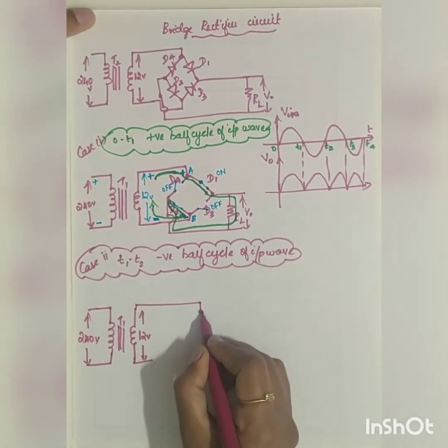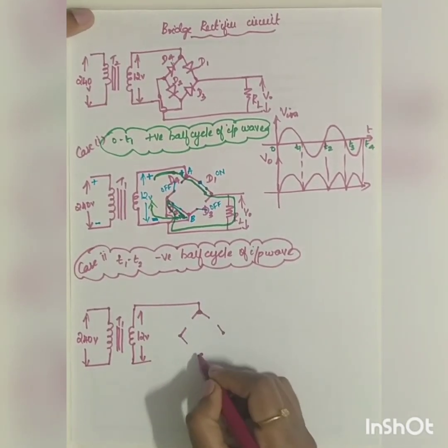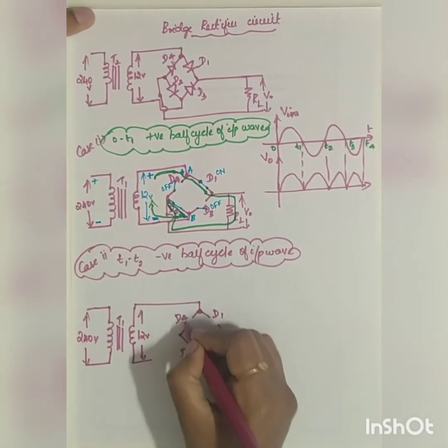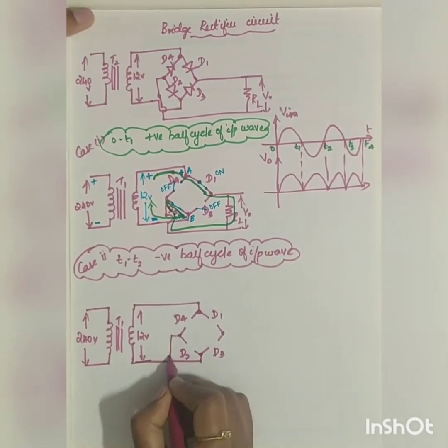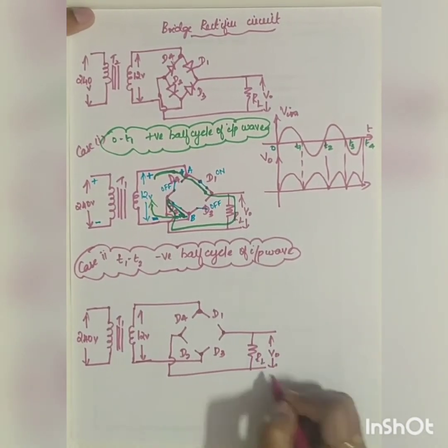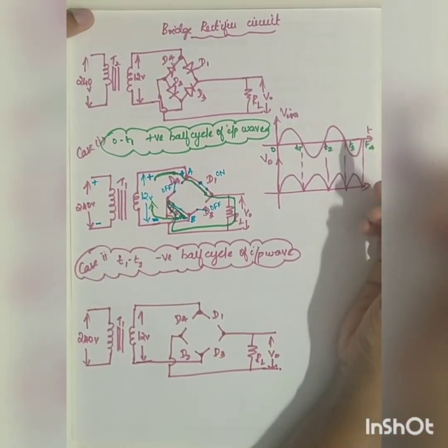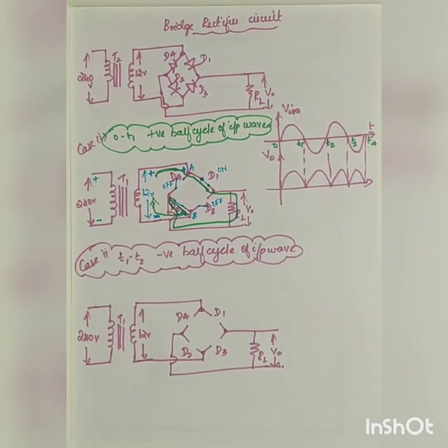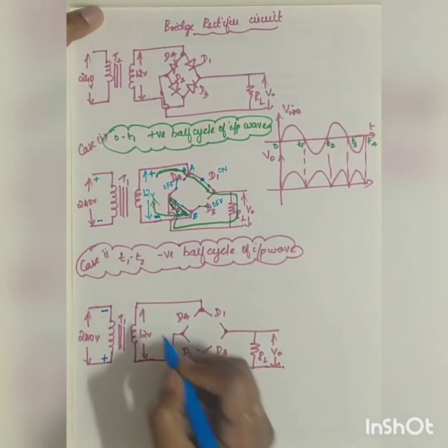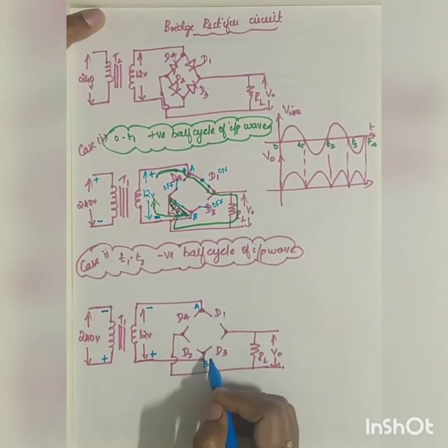Okay. Now here you can draw the 4 diodes. Let me leave space here. So here you have D1, D2, D3 and D4. Now it is connected to RL and here you have your V0 across your load resistor. Now let us take the next case, T1 to T2. You are applying a negative signal. So what happens? When the negative half cycle comes, here it will be negative, positive. Here it will be negative, positive, right? This is node A, node B, for easy simplification I am doing.